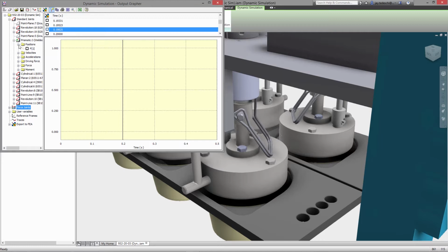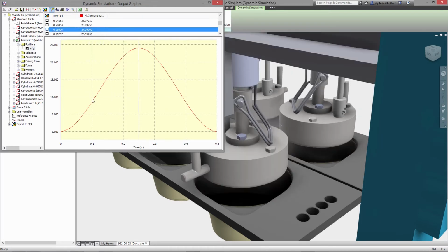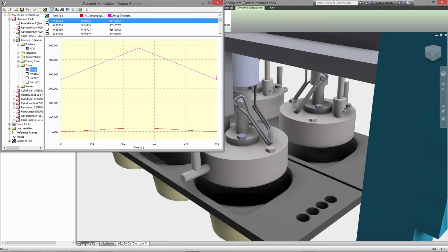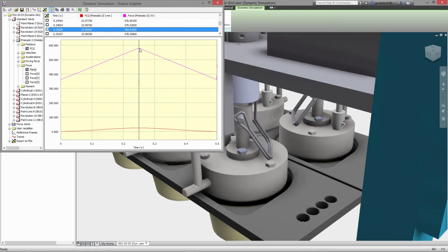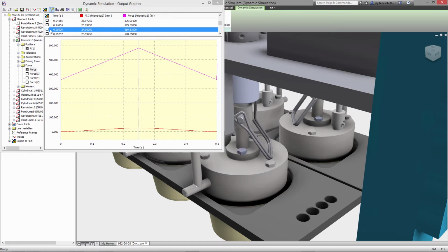This can be done by setting the position for a joint at different points in time, with full control over the acceleration profile. You can also specify what will occur outside of the defined profile, which is especially useful for equipment that operates cyclically, so results reflect operation between cycles rather than startup and shutdown.